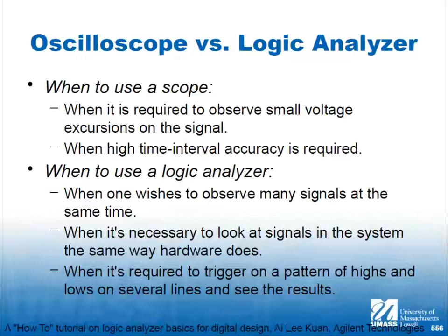You have the luxury in simulation of having the data all presented to you. In a working system, it's continuously running. So you need that trigger to say, hey, when FC comes on that bus, do this. Show me everything that happened before it and after it that will fit in the buffer. Maybe you want to bias it towards the end, maybe towards the beginning. That's based on what you're doing. And sometimes it's also a sequence of events.